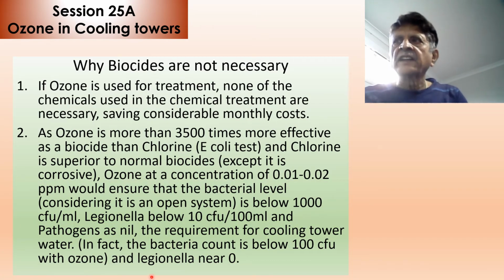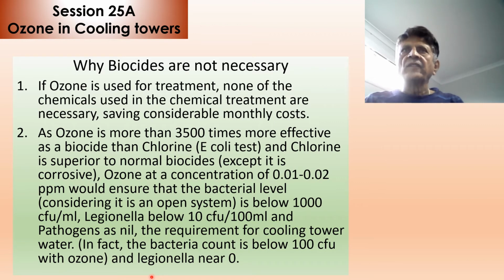Why biocides are not necessary if you use ozone? As ozone is more than 3,500 times more effective than chlorine using the standard E. coli test, and chlorine is superior to normal biocides, except that it is corrosive.